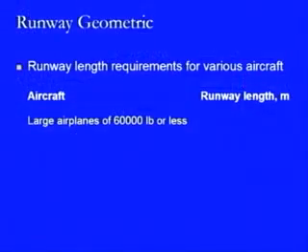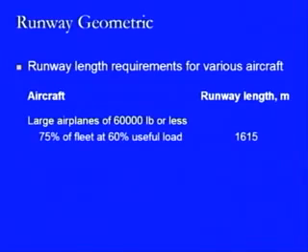Another case in the same category is a large airplane of 60,000 pounds or less. In that case, again it is dependent on the total amount of fleet which will be using the runway strip at a point of time, and that is like 75% of the fleet at 60% useful load, meaning the total loading is 60% with respect to that 75% of the fleet, then the runway strip required is 1615 meters.